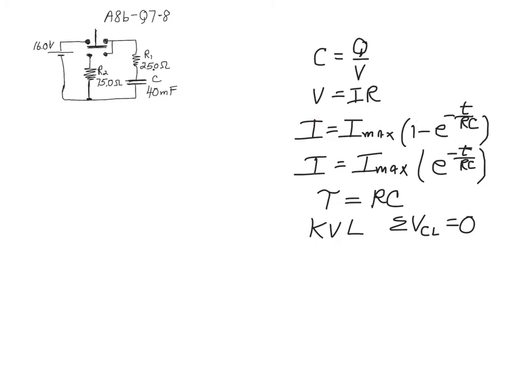So you really should understand the mathematics. When that exponential decay factor appears by itself this way, then you know that the current is going to start high and decay to 0. So the decaying behavior is this equation, and the charging behavior is this equation. You should know that just by looking at them, not really have to memorize it.